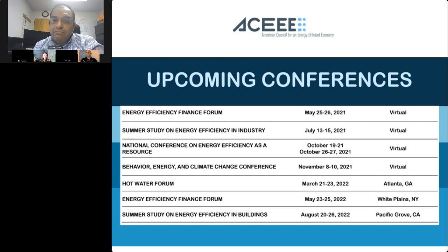So in the context of these commercial systems, if there is a potential to run the heat pump during the time when the ambient temperature is higher, then essentially you're going to see an improvement in the overall performance of the system. But again, the issue becomes, if you run it for a longer time, you obviously need the material to store that if you don't have the capacity. So the 2 options are essentially, one is to increase the capacity of the tank, or second is you can use the approach which I presented over here, like some embedded energy storage solution which can store the energy for later use.